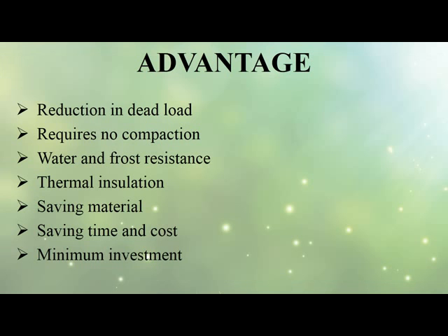Some advantages of foam concrete are reduction in dead load, requires no compaction, water and frost resistance, high thermal insulation, saving material, saving time and cost, and minimum investment.